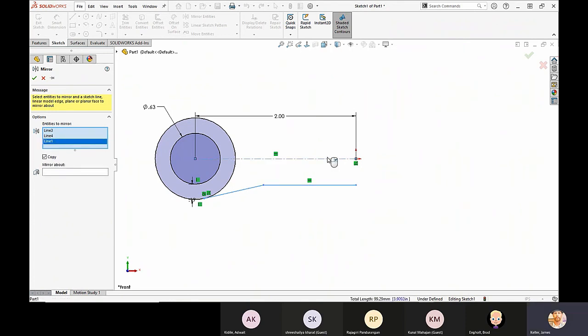So I'll go ahead and, oops, we need to select that box first. I can right click on that if I make a bad selection and either delete it, or I can right click and clear all selections if I'd like to. Go ahead and click in this box right now to make sure that it's selectable. And then select the center line, and you can see the preview of that geometry is now up here.